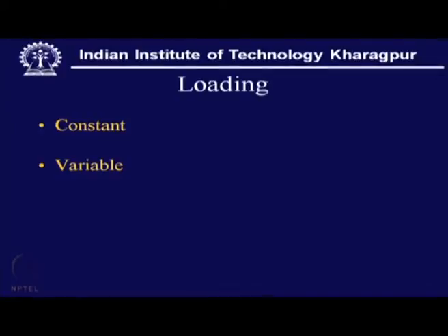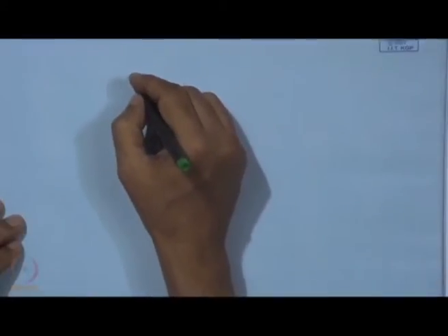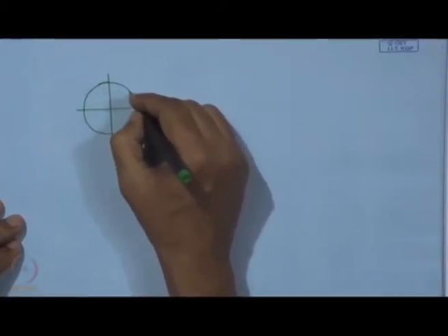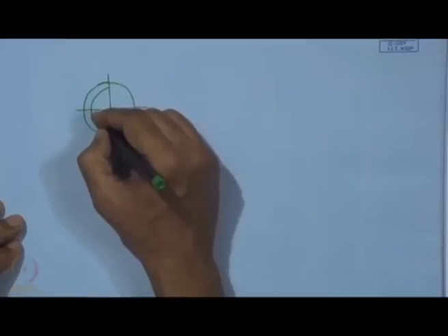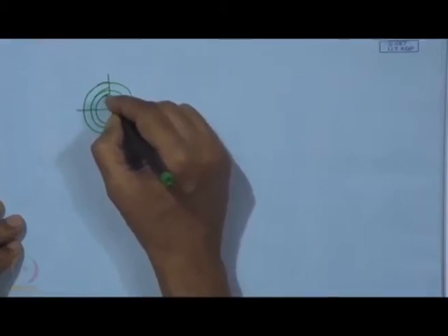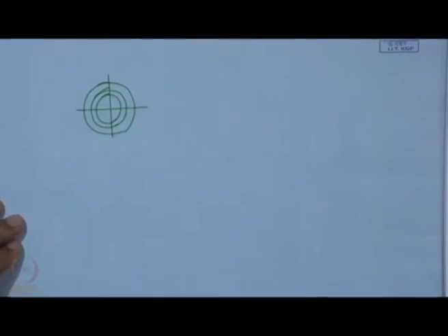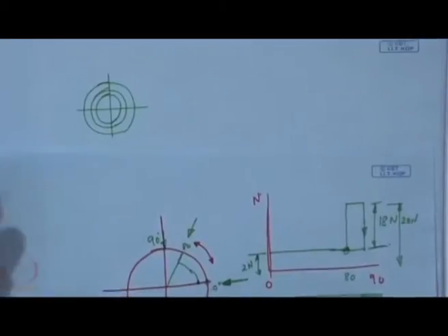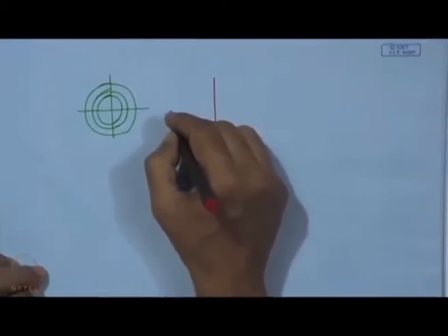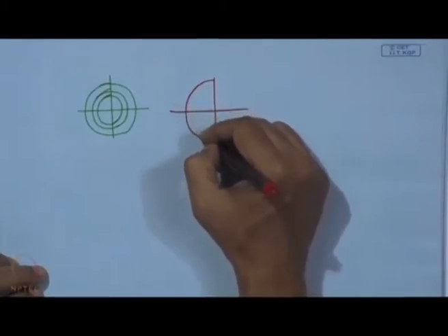Now, here what we can see, that in normal case we expect a wear track of uniform width. However, when it is this type of system, a special tribometer, this is for a conventional tribometer, and which has a unidirectional movement, but when it is this reciprocatory tribometer with alternate sliding, in this case we do have